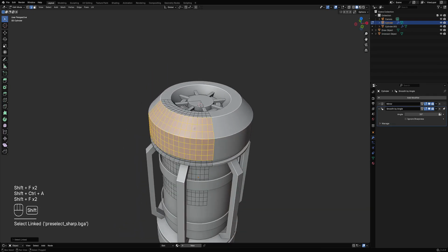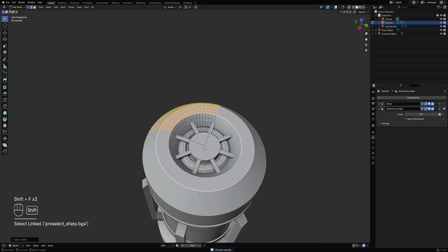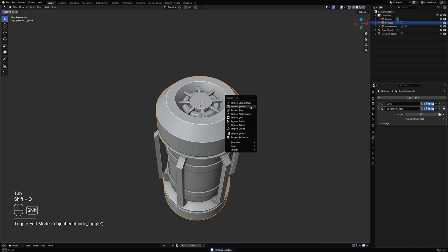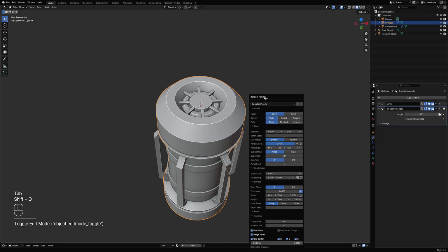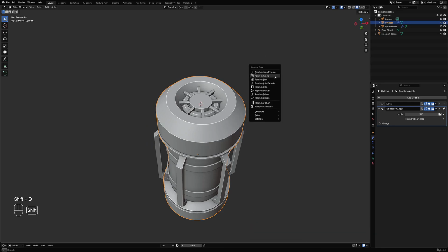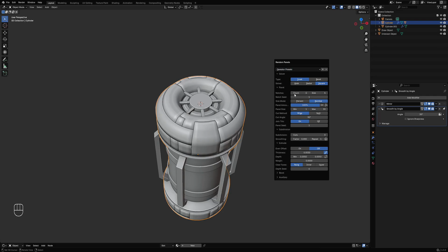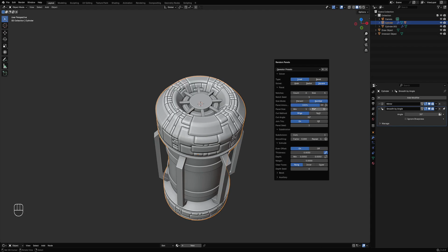And yeah, this is the add-on pre-select using Shift F. You can download it in my Patreon for free. And it's a support tool for random flow. I'm going to use random panels. I have auxiliary on and use this and then toggle on even offset. To make the islands bigger, you need to increase the panel size.